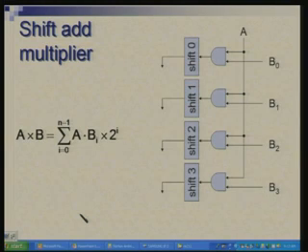So, each of these shifters is doing shifting by a fixed amount. All right. So, there is no active logic here, it is only appropriately wiring it. These shifters do not have to select between shift and no shift, it is a fixed shift which each is doing. So, it is simply a matter of wiring it appropriately, so that effectively shift takes place.